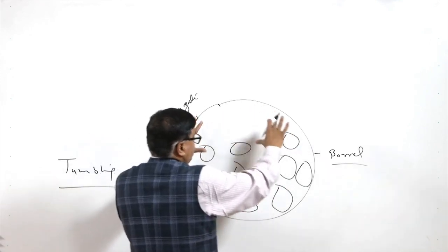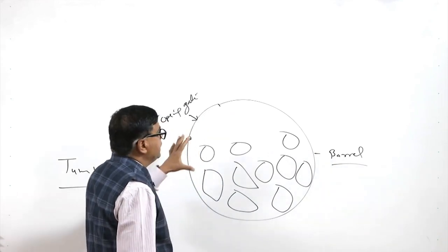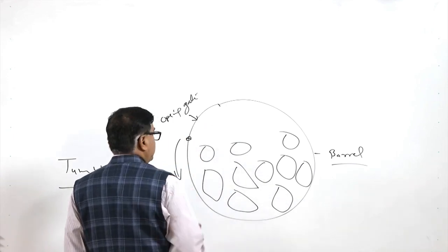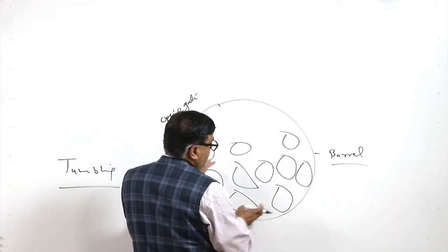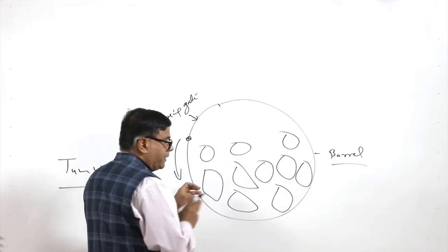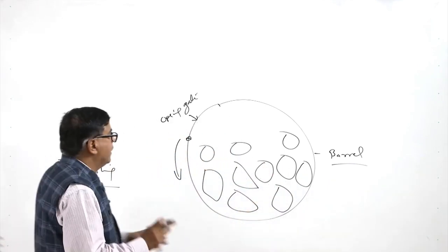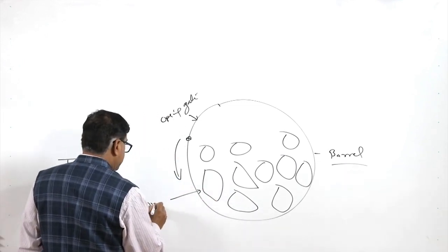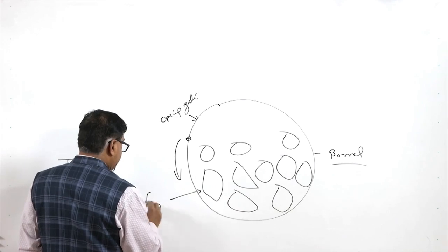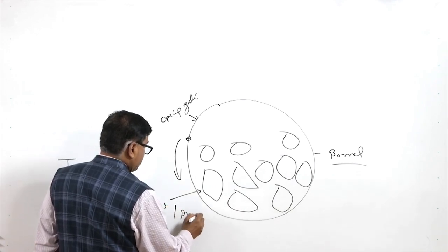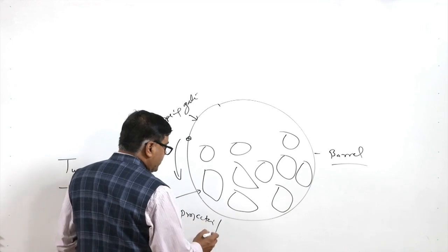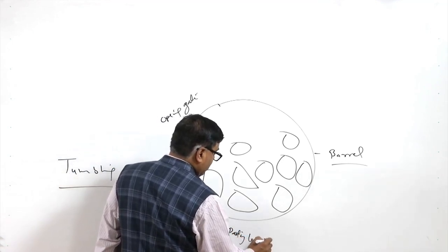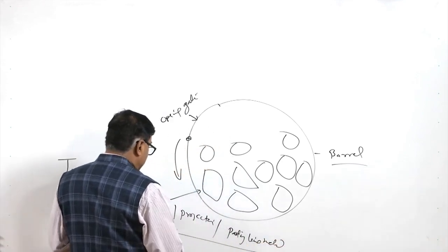and enough space is kept empty in the barrel, so that when the barrel is rotated, the surfaces of the castings will be coming in contact with each other and they will be rubbing each other. So, in this process all the fins or the projections or the additionally deposited metal at the parting line, all those are easily cleaned.